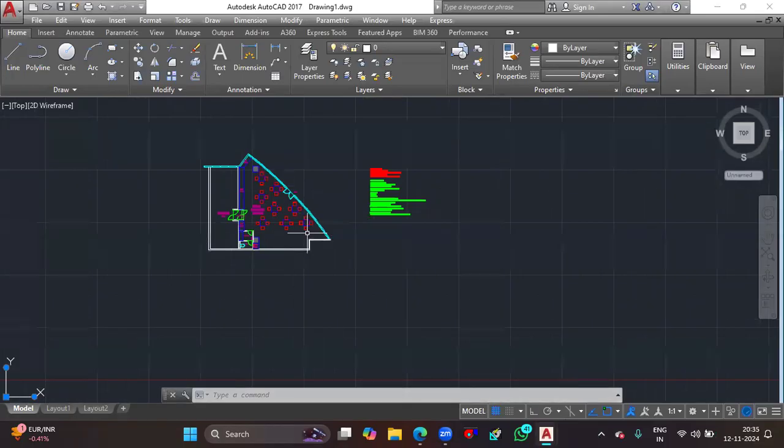From the Excel sheets, you get a tonnage value according to the CFM range. On the Excel sheet, we got a tonnage of around 6.2 ton according to the CFM value, isn't it?